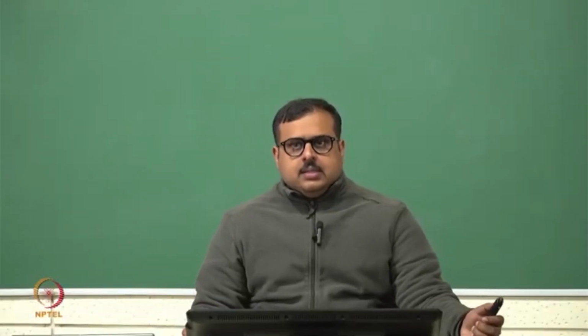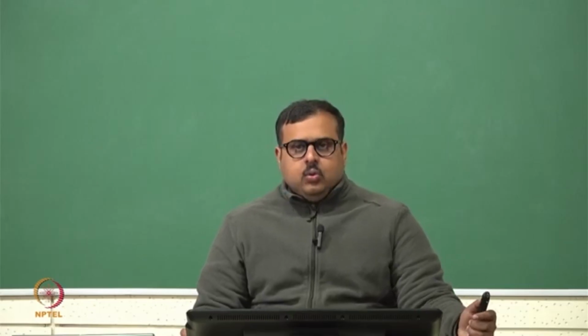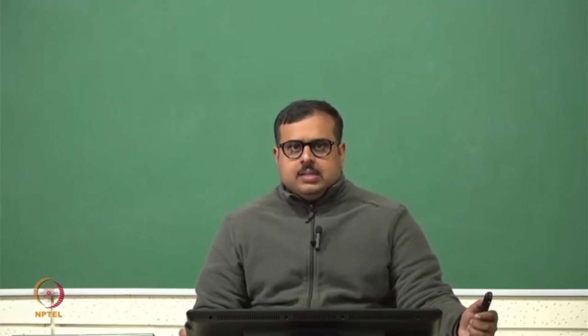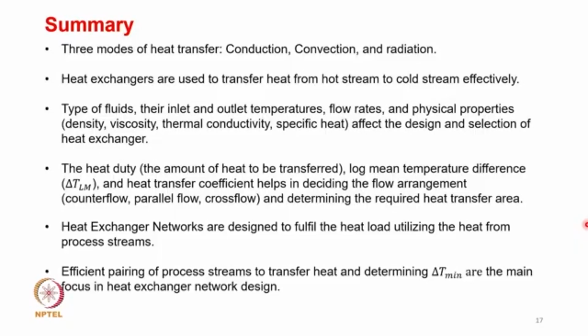Just to summarize, with this I think we would conclude today's session, and let's summarize the key points that we have learned. There are 3 modes of heat transfer: conduction, convection, and radiation. And next, heat exchangers are used to transfer heat from hot stream to cold stream effectively. Types of the fluids, their inlet and outlet temperatures, flow rate, and physical properties such as density, viscosity, thermal conductivity, and even specific heat can affect the design and selection of heat exchanger.